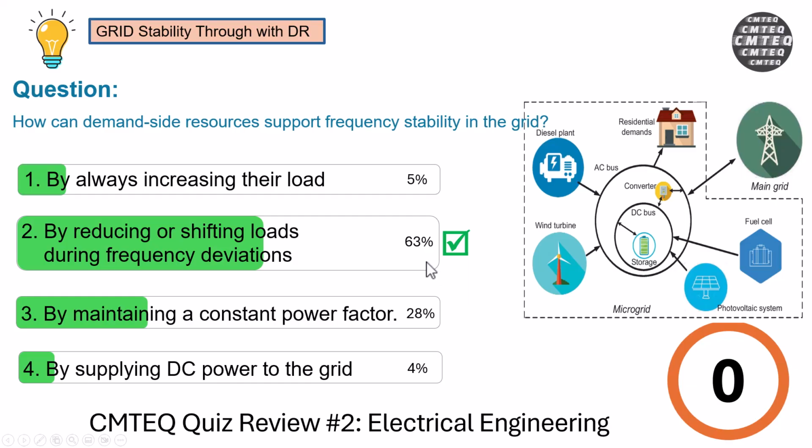Let's go ahead and elaborate. Simply put, the demand response, or DR, is very crucial for grid stability and managing the smart grid system. So this program basically allows large aggregated consumers, people who need lots of power, to reduce load during under frequency events, when those things happen. So this basically helps the grid in terms of rebalancing the supply and demand without adding additional generation into